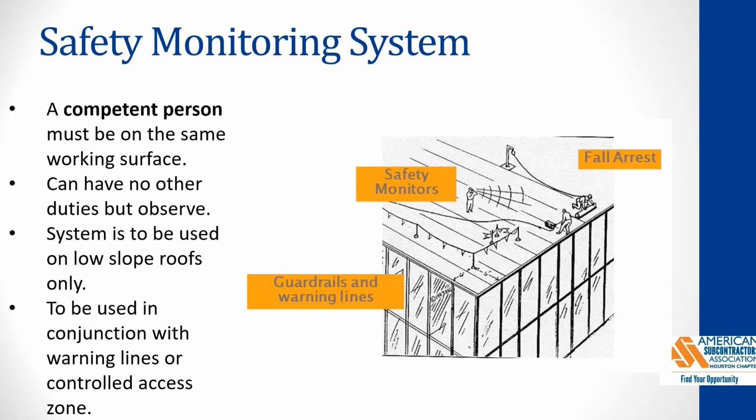This system is to be used on low-slope roofs only, and to be used in conjunction with warning lines or controlled access zones. If using this system, your employer will give you proper training.